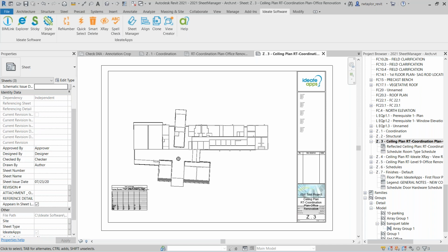So it will use the room calculation point. In that particular case, I'd have to look at how that was set up, the family, but I'm going to say the answer should be yes, because again, if you're using the doors and you're doing the room calculation point, that's where it's getting the from room and to room. And if you're switching the from room and to room, it will actually flip the door swing if the family has been created that way using that room calculation point.